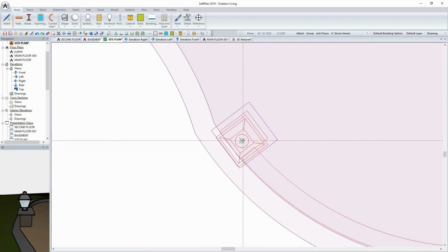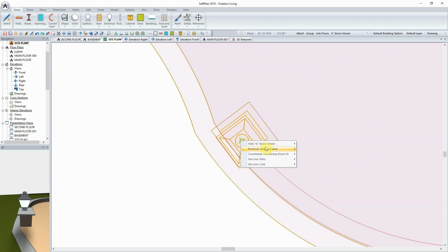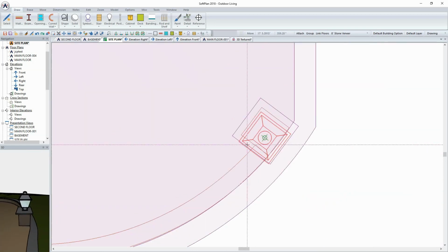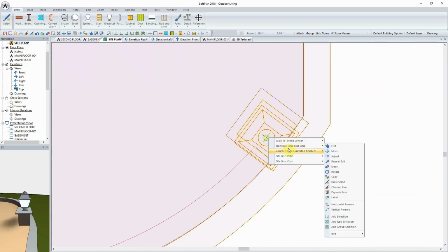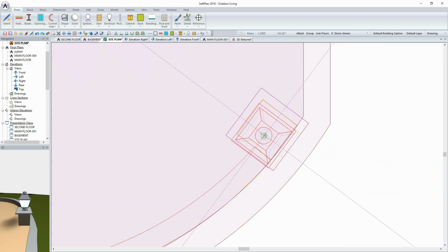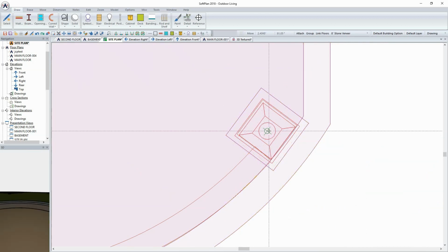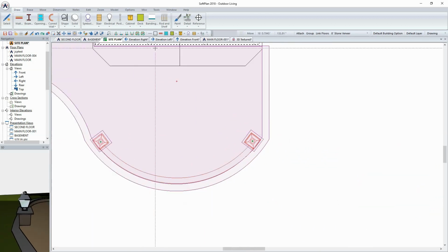And so now I can just move this into place as needed, and so I'll just select the move option, remove my lock, and position it over the actual base itself, and do the same thing here. Just select the actual lamp post and move, and remove, taking the F12 function key off, to be able to see what we've got.